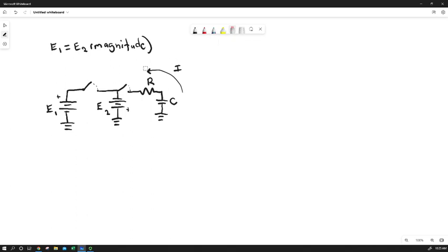Now, from the point of view of the way we would achieve this in an experiment, let's get another color here. We could use our picoscope or any oscilloscope function generator combination, a function generator for whom we would view the signal with our oscilloscope, of course, and we could create a periodic square wave voltage signal.